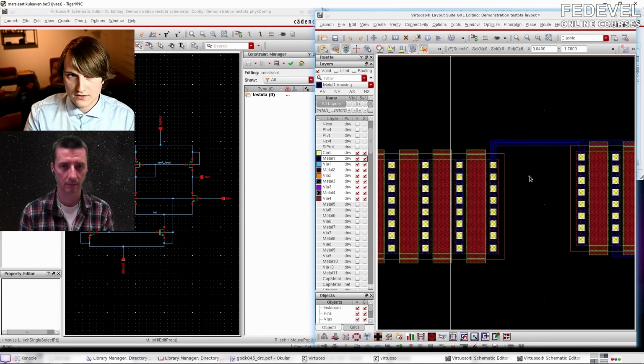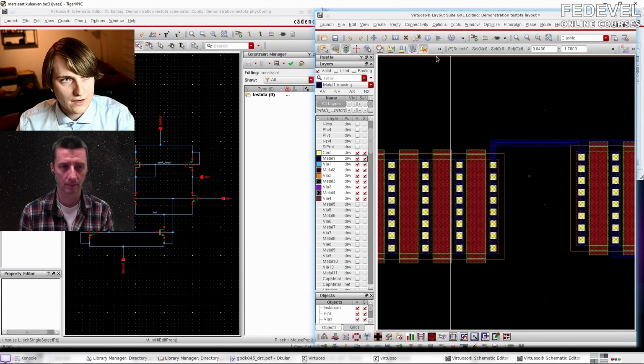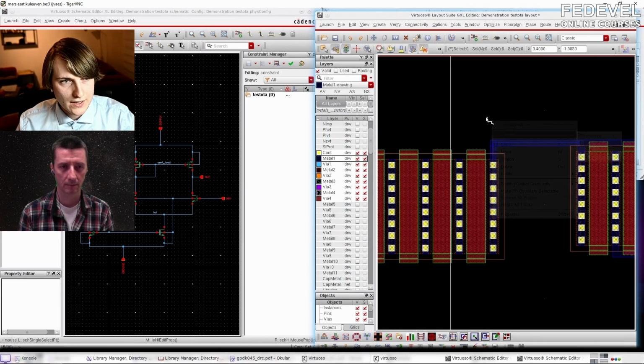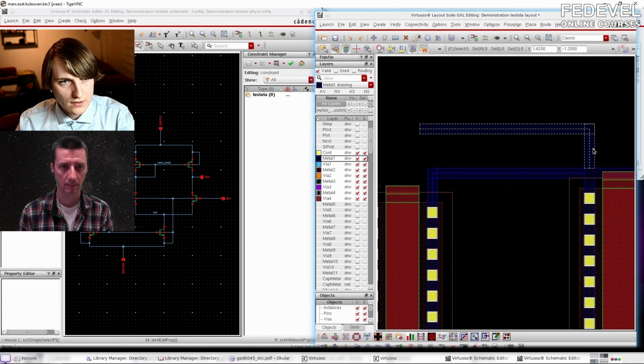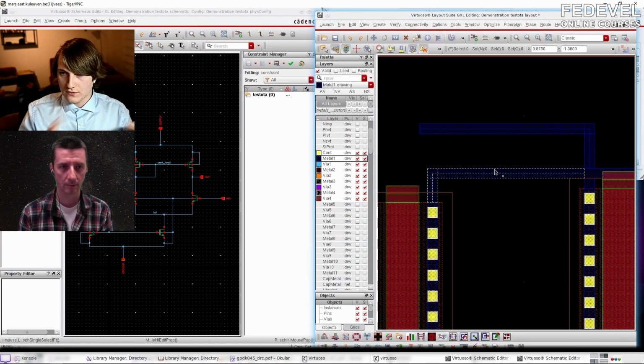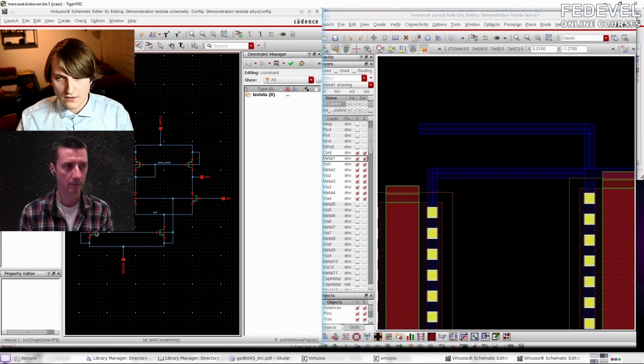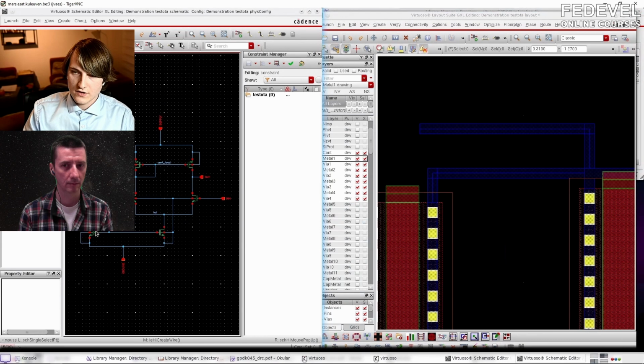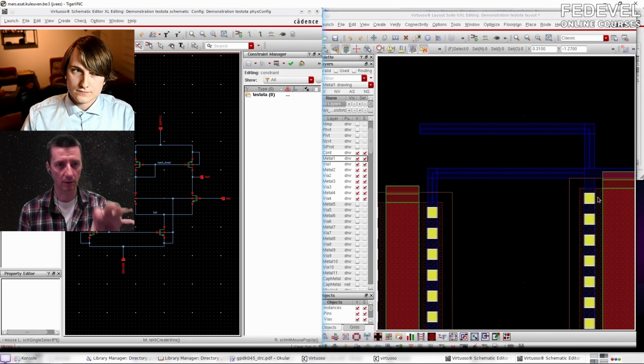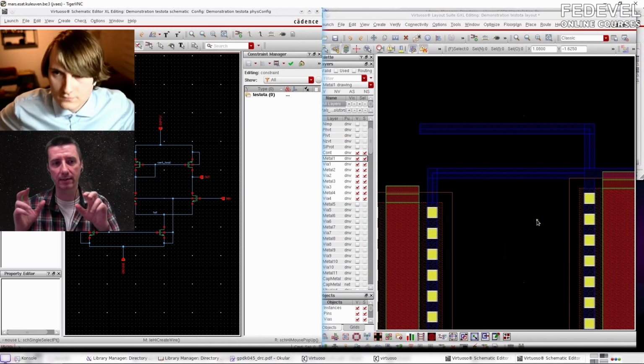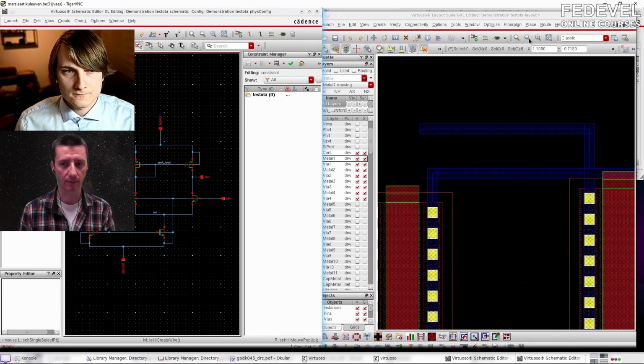This is a very long simulation with a tool, again with information provided by the foundry. If I now create another wire here, it'll say that there's a capacitance between this node and this node. Then it will make a new schematic where it places this cell and adds all of these new capacitors and resistors. Then I can go back and do the simulation I just showed you again, and see how my performance changes. So you don't really simulate the chip itself, you always simulate the schematic, but together with all the extra components created by the layout of the chip.